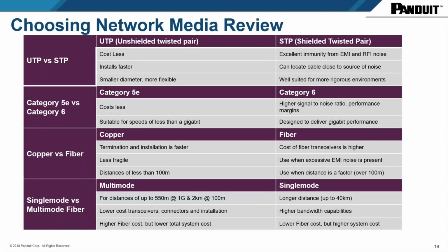When you look at the fiber, having single mode versus multi-mode also is determined by how far you could run these cables. Multi-mode fiber, for instance, could take you up to 2 kilometers. When you go single mode, and that's a very expensive type of cable, you could go to 40 kilometers. So again, the determination of when to use shielded versus unshielded, copper versus fiber, a 5E versus 6 versus 6A, all of these different specs have to be taken into consideration.